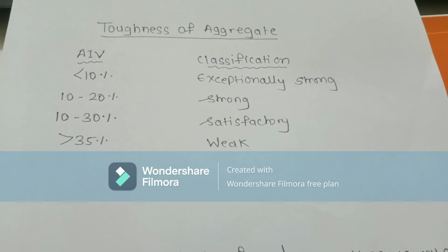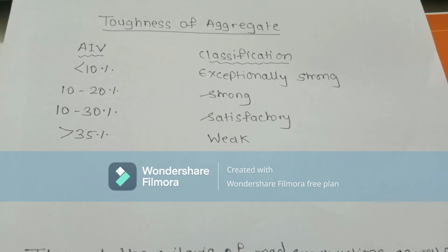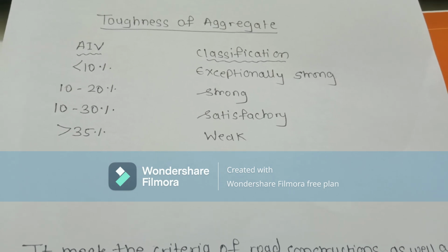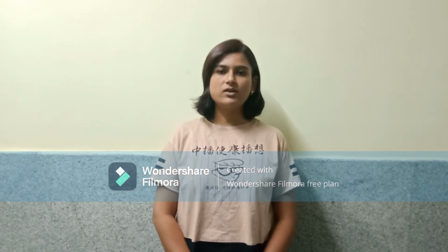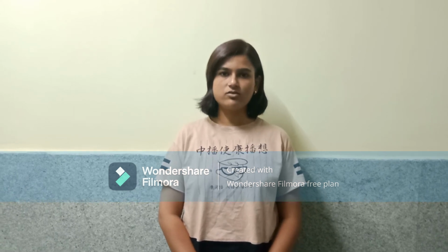As our value is between 10 to 20%, from this table of toughness of aggregate, we can conclude that our aggregate is of strong type. So from the result of the aggregate impact test, we can conclude that it is suitable for road construction as well as some concreting works.